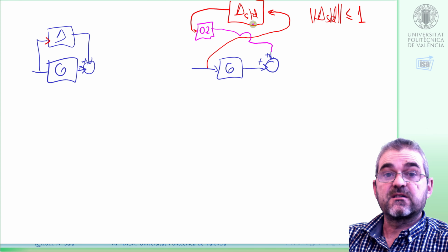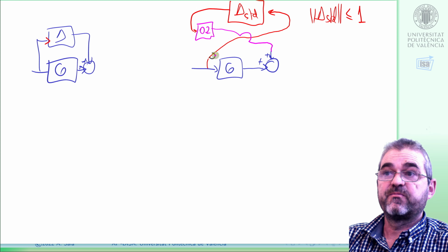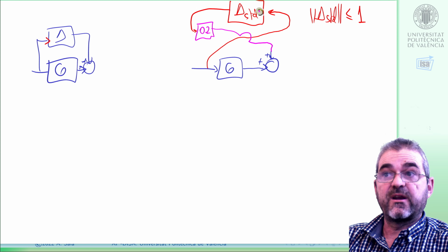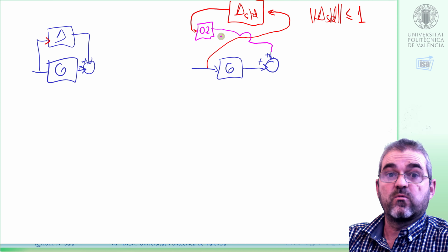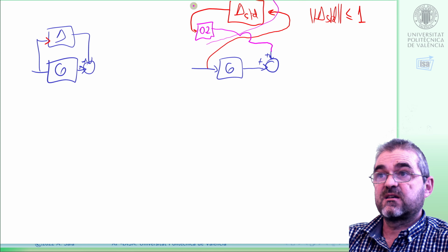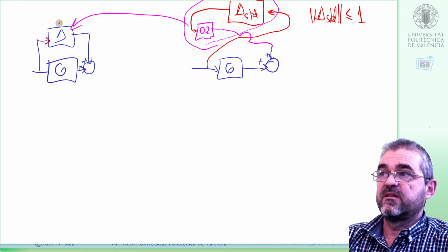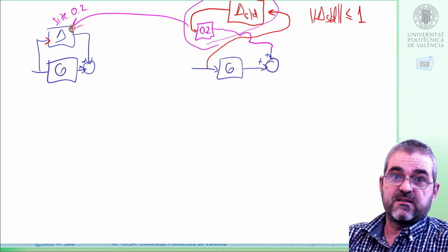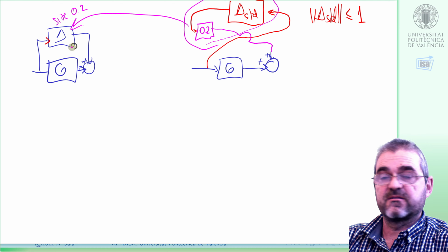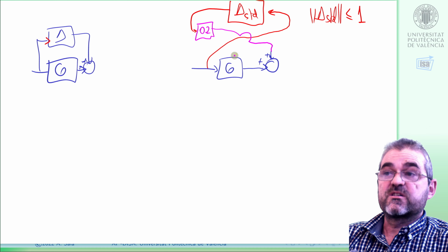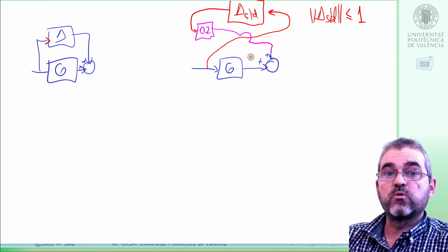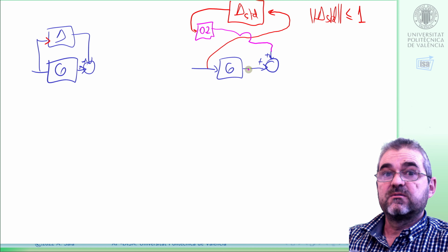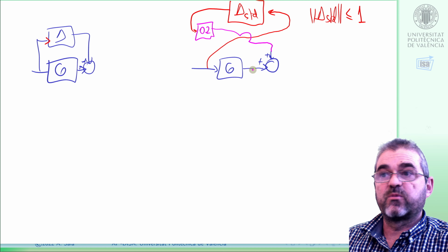This is the same as an uncertainty of size 0.2, you know, something enters through an uncertainty whose worst case gain is 1, and then if I multiply by 0.2, the worst case gain of this everything will be the non-standardized 0.2 uncertainty. But okay, we express it this way because, you know, scaling so that we are comparing to 1 is the way to go in H-infinity multivariable problems.